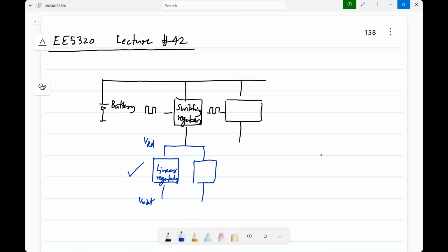Linear regulator is basically a negative feedback amplifier. Okay. You have a reference voltage usually generated from a band gap reference, and you scale it up to the right value by using an amplifier with some gain, whatever gain that you want. Okay. So essentially everything that you know about negative feedback amplifiers can be applied here. There are some special constraints in that typically for a regulator, the load current will be only in one direction and it can vary widely.